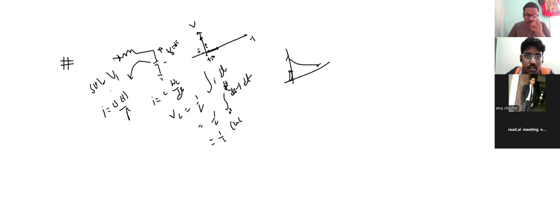Okay, fine. So at exactly t equal to 0, the cap is shorting. Any reason at t equal to 0? Why is it shorting? Because at 0 time, we can say infinite frequency is there, and the impedance of the capacitor is 0. So we can short it to ground. I said there is no initial voltage across the capacitor, it could be 0. And also here there is nothing, no extra circuit, so it is a direct impedance short. Impedance of cap is 1 by C omega, omega tending to infinity, so it will become 0. So infinity is mathematically 0. Mathematically, okay.